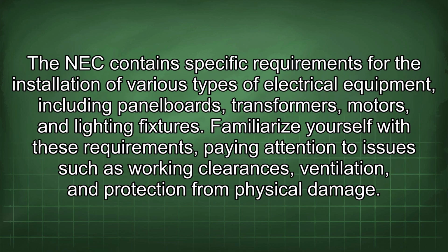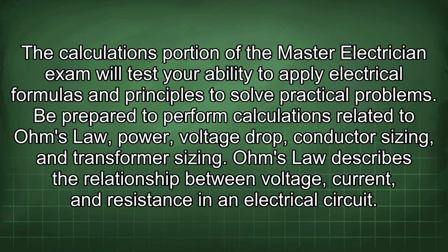The NEC contains specific requirements for the installation of various types of electrical equipment, including panel boards, transformers, motors, and lighting fixtures. Familiarize yourself with these requirements, paying attention to issues such as working clearances, ventilation, and protection from physical damage. The calculations portion of the Master Electrician exam will test your ability to apply electrical formulas and principles to